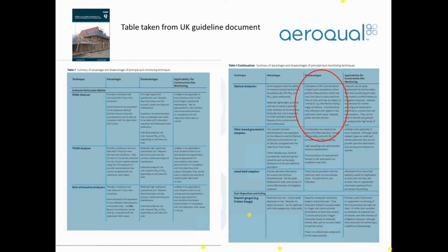So what they are referring to here is that if your instrument is placed in one location and it's measuring silica dust, and it's placed in another location and it's made to measure a carbon dust, the instrument is going to respond differently. So this is really what it means. So how do we get around this problem? How do we improve upon the accuracy of our optical method, given all of the advantages it has? That is the real time, the low cost, the ease of deployment. How can we mitigate some of the disadvantages?